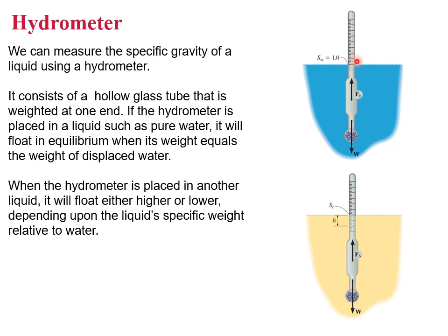And then you use that as kind of a gauge. So if you put it in any other kind of liquid, it's going to rise or fall depending on what the density of the liquid is. It depends on the specific weight relative to the water. It'll sink lower or sit higher depending on if the density of the fluid is greater than or less than water.